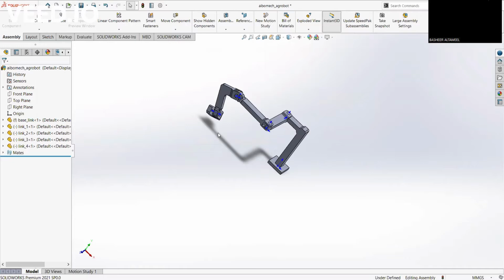Today I want to explain to you just how to convert a SolidWorks sketch to URDF, so that we can use it in our programming in Robot Operating System. I faced a lot of difficulties in this: the axis selection and the plane selection that we sketch on, because the URDF plugin in SolidWorks requires exact and specified features and properties, like constraints, that we have to follow.